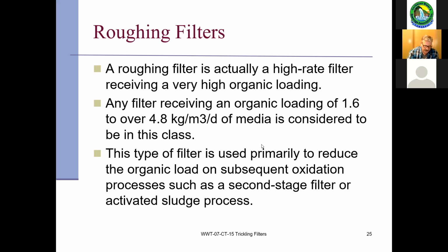In the example I provided with a fruit processing plant or a packaging plant, if you didn't have some kind of pre-treatment, whether it be a trickling filter, for example, that organic load hitting the system will basically overload your biological process. So you need something to take that load off in the first place.